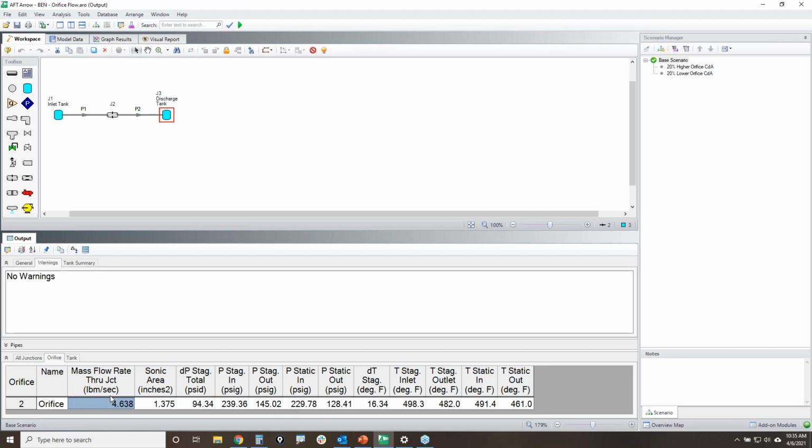So this is slightly lower than the choked flow mass flow rate, which was 4.646. All right. So now I know that somewhere between 90 and 80, that's where I'm going to have that critical pressure where I start choking. Not critical pressure as in critical pressure and critical temperature. I'm just using the word critical to emphasize that's the pressure where we first start to sonically choke.